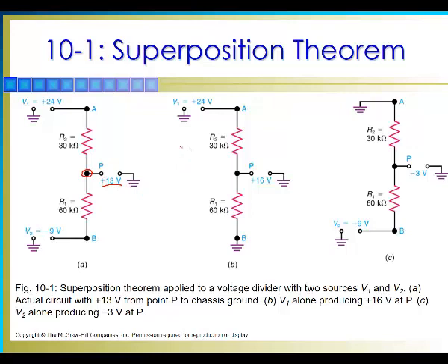It's by doing the analysis by eliminating one source at a time. So we have two sources. For the first part, we can eliminate this V2 and connect a straight line from here, like a short circuit. Okay, we short this source like this and connect it directly to ground. Now we have a circuit that has only the two resistors and the one voltage source of 24 volts.